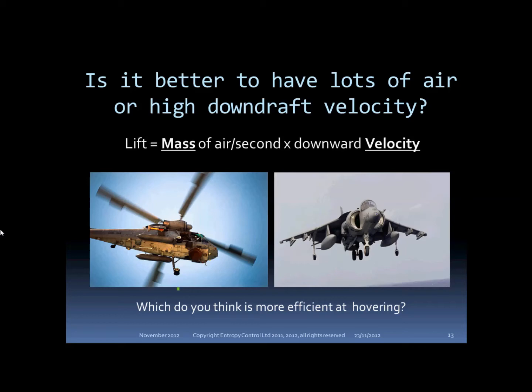The Harrier aircraft on the right is held up by Bristol Pegasus engines that blast quite small amounts of air at high jet velocities. To give you an idea, the jets consume about a pound of fuel per hour per pound of thrust. So if the Harrier were 100% fuel, it could hover for about an hour. In practical terms, the Harrier has to be lightly loaded to hover at all, and its hover endurance is certainly not more than about 10 minutes.